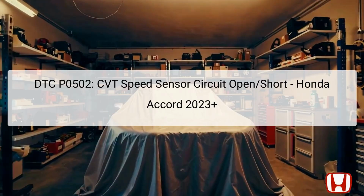The Diagnostic Trouble Code, or DTC P0502, indicates an issue with the continuously variable transmission CVT speed sensor circuit in the Honda Accord 2023 Plus. This problem arises when the transmission control module, TCM, fails to detect the signal from the CVT speed sensor while the secondary driven gear is rotating, suggesting a possible open or short circuit condition.